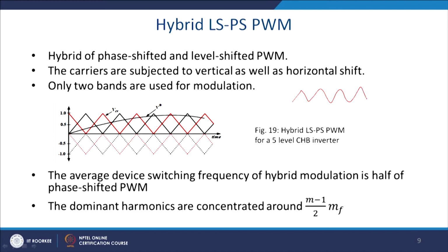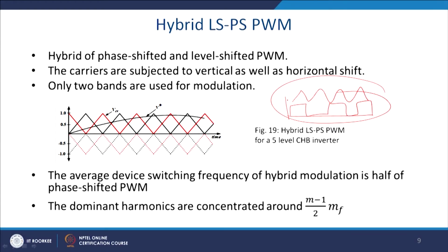So, now there can be another solution to it. Instead of this requiring little complex circuitry, every quarter cycle you have to give a phase shift, sorry, you have to give a DC boost. So, ultimately what happens is quite easy. You have this one and you have a square wave. You add a square wave, it goes up, then again it comes down, then again goes up, then again comes down, like that. So, you have to add these 2 cycles. Okay. So, this is the way we generate the previous modified phase level shifted PWM.